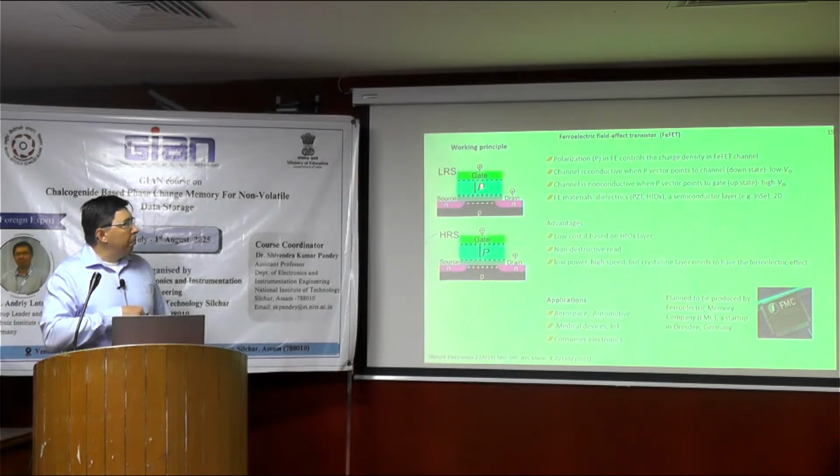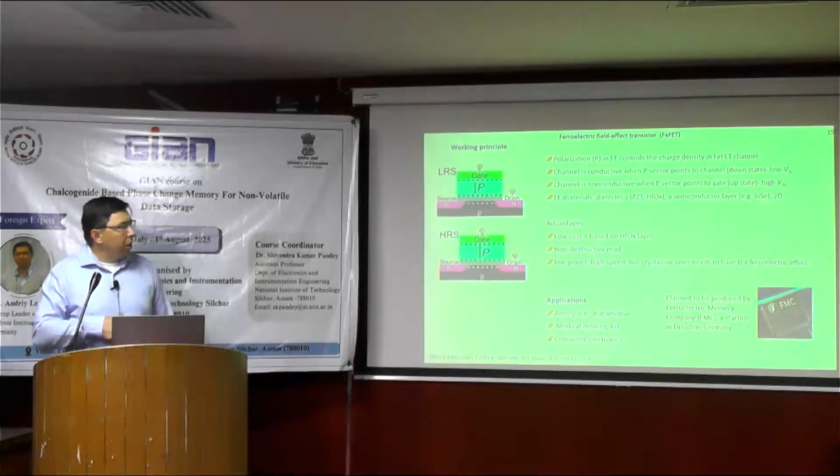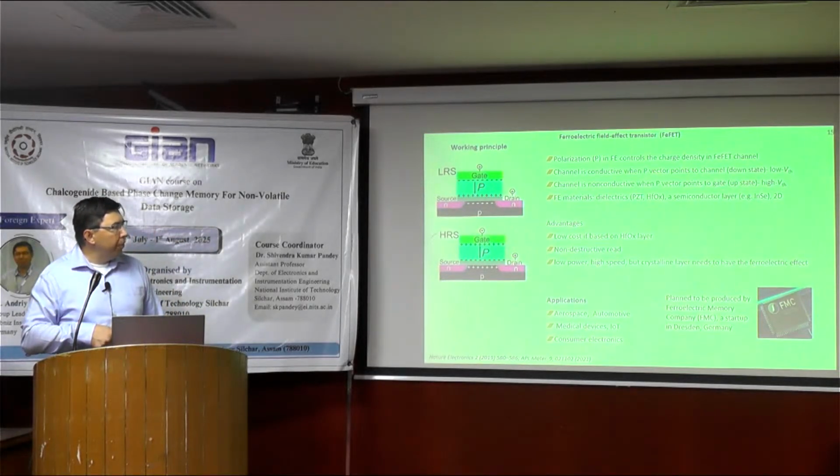Then the P polarization vector points to the channel in the down state, and the channel is non-conductive; if P points to the gate, the channel is conductive. And here again, ferroelectric materials are used. These are PZT, hafnium oxide, or some semiconductor layers, indium selenides and 2D materials.